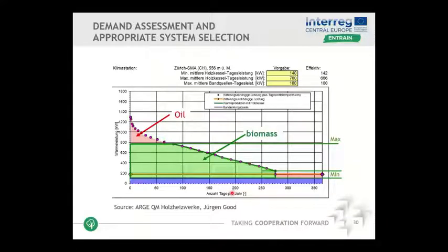So we have to ensure that we operate our biomass boiler, especially the biomass boiler, within all load ranges in the defined operating conditions. So that the biomass boiler is not going into start and stop operation, and is not going below the minimum allowed load rate of this boiler. Of course, maybe I have to mention this, or I jump onto the next slide.